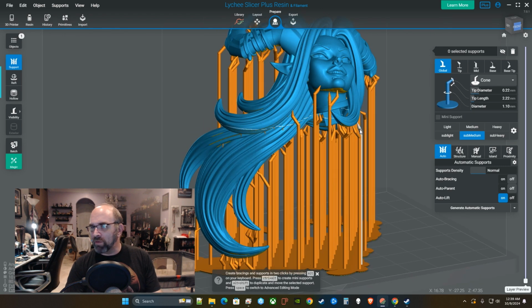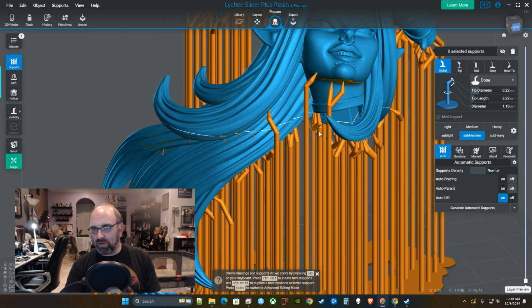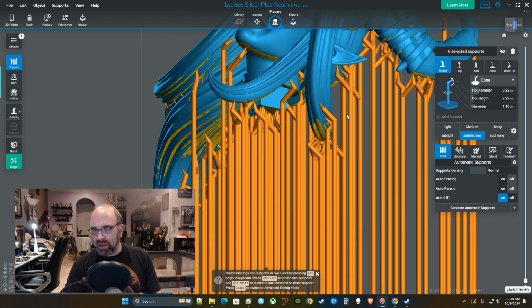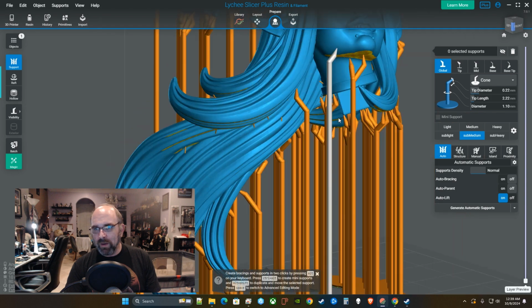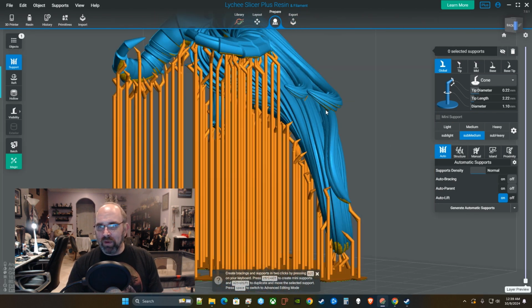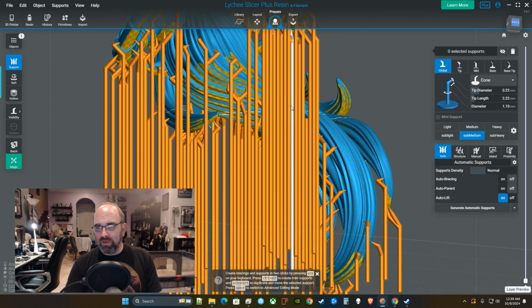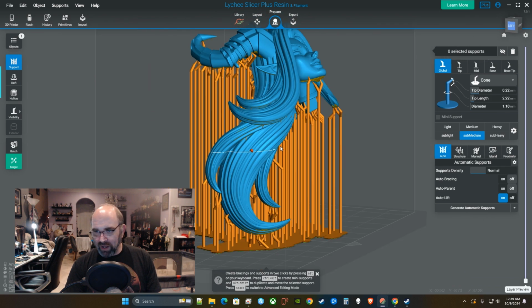And this is smart because that's a bit of a string. See, again, it's not perfect, but this is what I'm going to teach you. If you ever see weird supports stringing off like that, definitely delete them. They don't need to be there. And for the most part, that actually did a pretty good job of covering most of the areas.